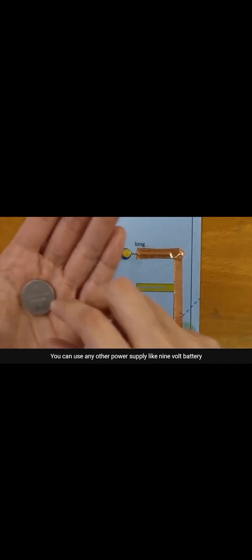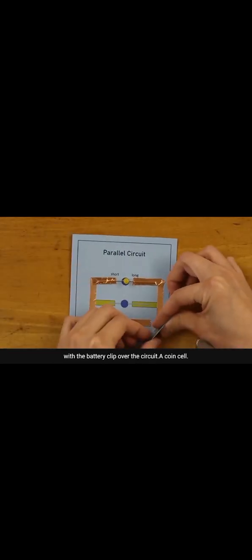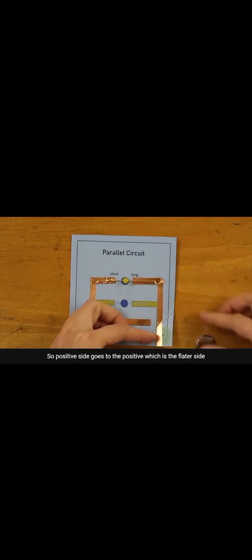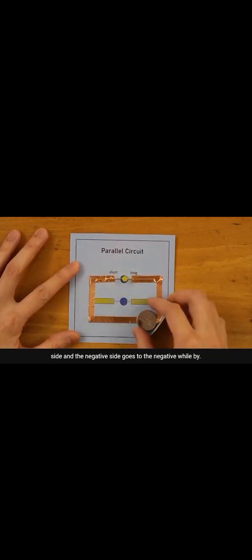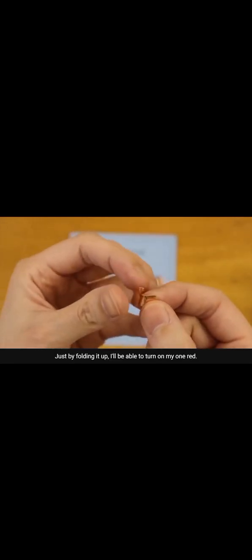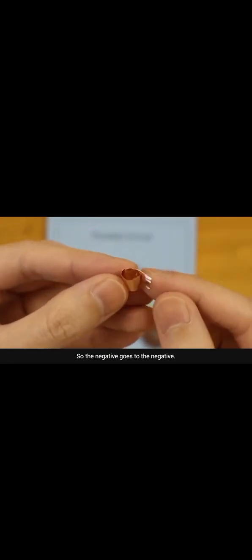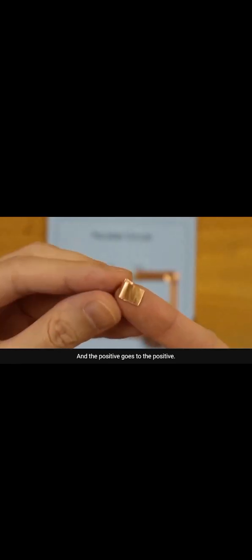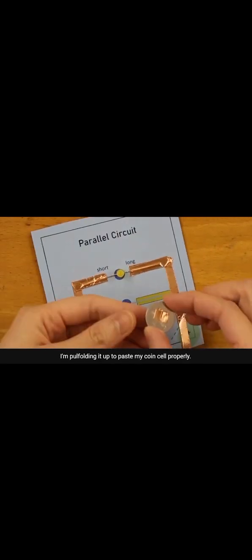You can use any other power supply like a 9-volt battery with the battery clip over the circuit. With the coin cell, the positive side goes to the positive, which is the flatter side, and the negative side goes to the negative, and by folding it up I'll be able to turn on my one LED. So the negative goes to the negative and the positive goes to the positive. This is a copper tape. I'm folding it up so I can paste my coin cell properly.